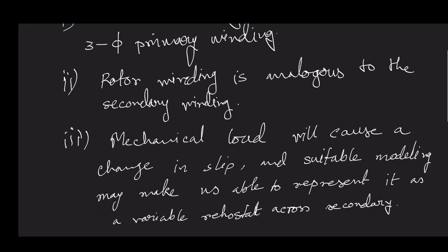you can understand that when we are talking about active power, even in case of alternator, active power requirement is taken care of by the prime mover. Your field winding cannot do much in terms of active power. Field winding current cannot do much. I'm talking about synchronous alternator. Now, alternator converts mechanical energy into electrical energy, and electrical active power requires mechanical prime mover input.